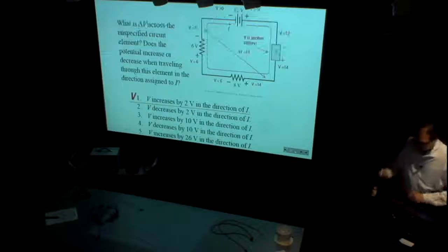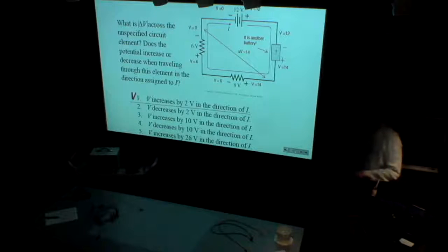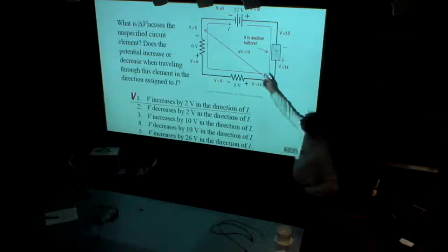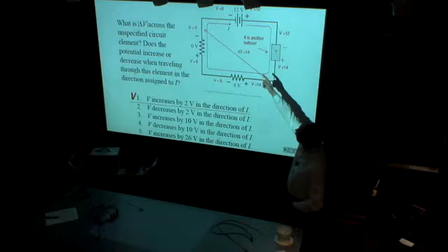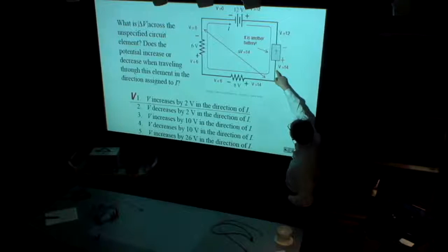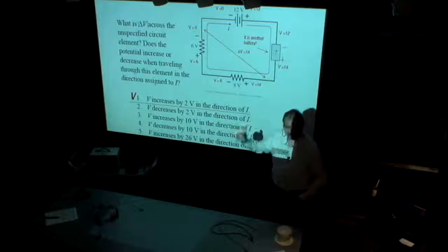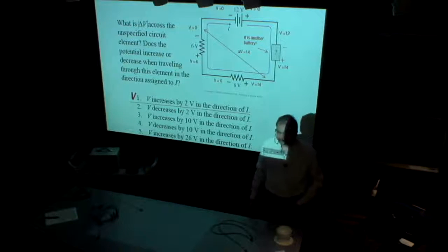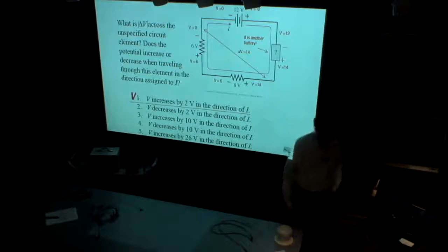Well, and very quickly, exactly the same reasoning tells us, so 0, 0 plus 6, 6, 6 plus 8, 14. This electric potential equals 14 volts, but that's 12, how can it happen? That's not a passive element anymore. That's supposed to be a second battery.